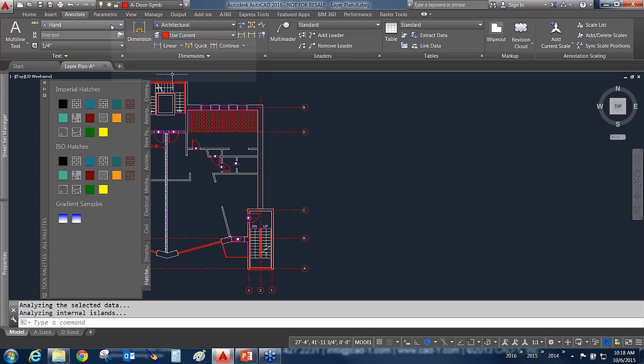But if I've already done all of that once, I can plug some of that information in here, into my tool palette, and the next time I drag and drop, just like I did with the hatch pattern, it remembers all of that. It remembers the text style. What if the text style doesn't exist in the drawing? The program will create it for you on the fly.